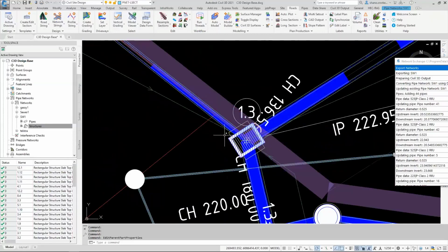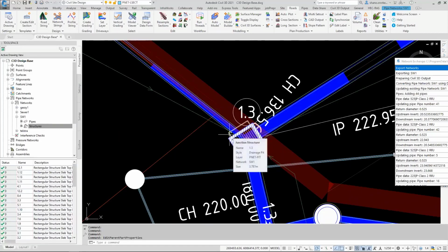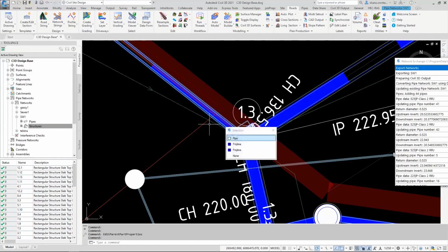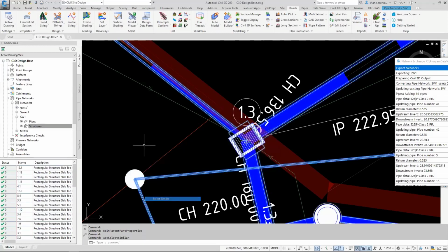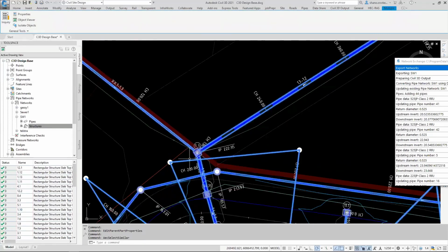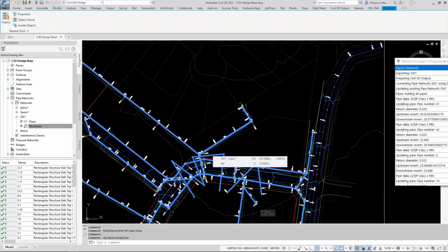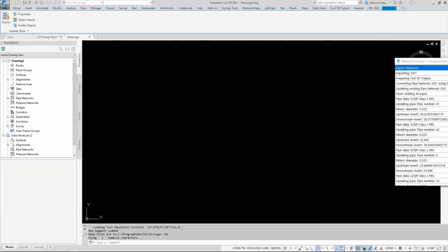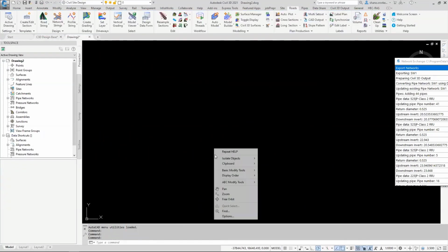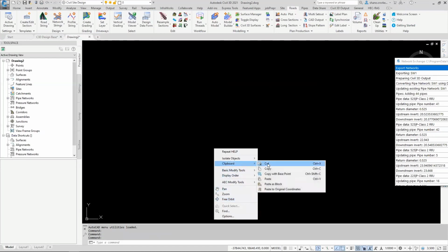In Model Viewer, there is an option to import a CAD file. So you can export those solids from the Civil 3D pipe network, put them in a separate drawing, copy and paste original coordinates, and then in Model Viewer, you can show that CAD file. That way, if you are working with pipes and pits that are not just your primitive cubes and cylinders, you can show them in that way.